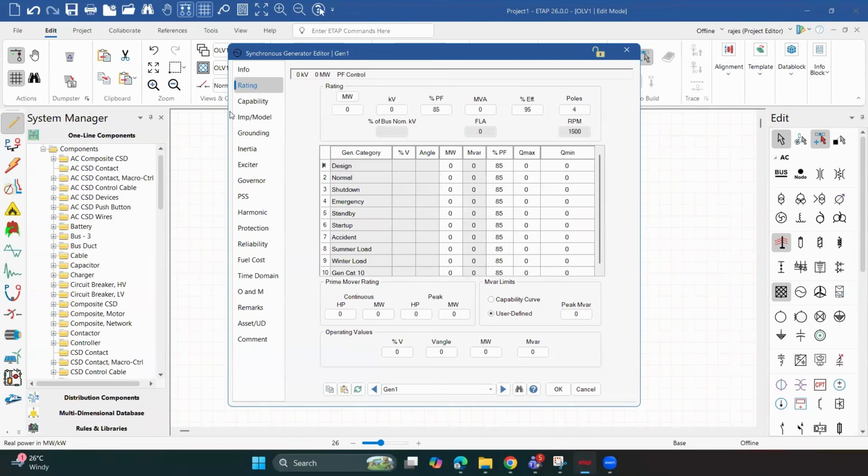800 megawatts. I guess what I have done is I have cancelled it. I have not given OK. Right, 800 megawatt corresponds to 495 MVAR at 0.85 lagging power factor, and 0.95 leading power factor corresponds to minus 262 MVAR. That is what I have given.